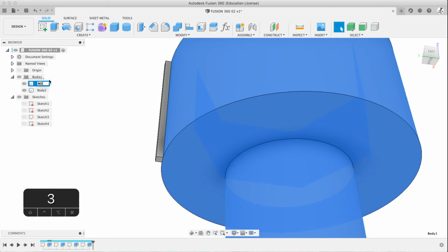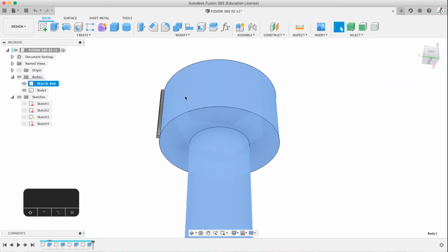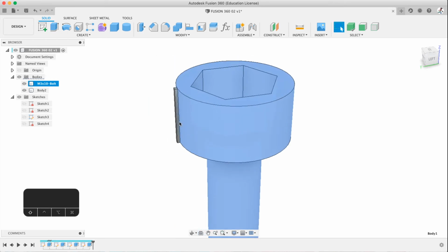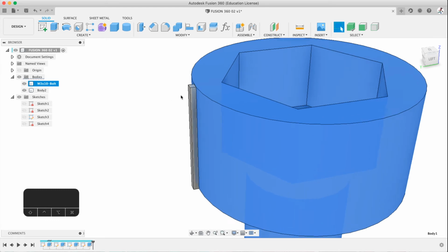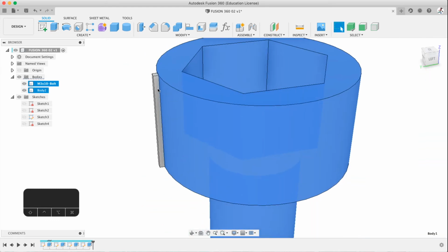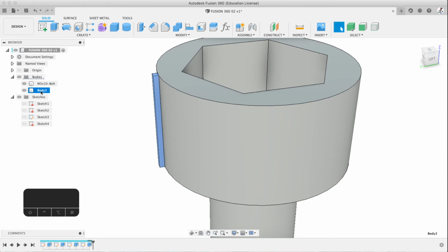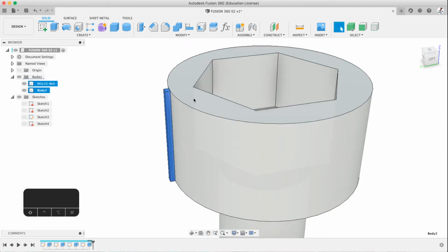Let's go M3 by 10 bolt, or actually no spaces. There's a coding thing, underscore or hyphen, whatever you want, bolt. If you don't do it, that's fine. It's just naming conventions, when you get more professional about this kind of stuff, it's really important to follow naming conventions. Try not to use spaces. It's just a quirk. So we're set. M3 bolt. This will just disappear in a second. I'll show you. So here we go.